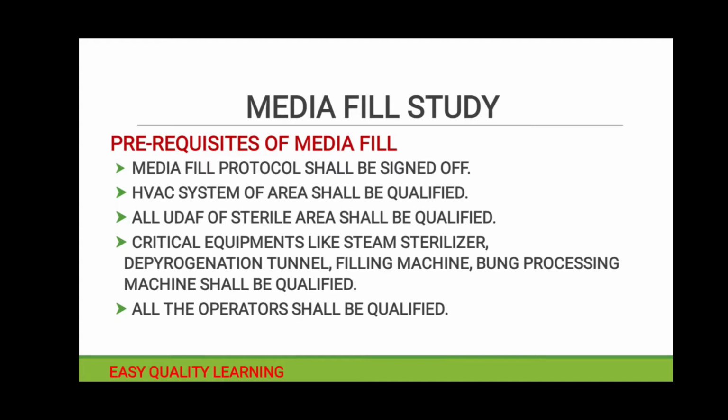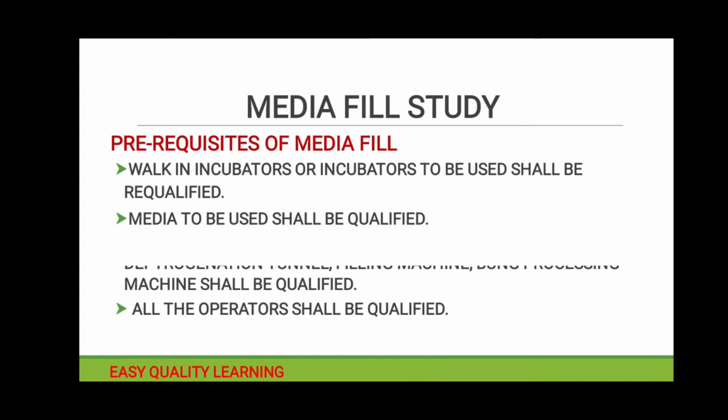Then all the critical equipment which is used in aseptic processing, like your steam sterilizer, depyrogenation tunnel, filling machine, and bung processing machines, all these machines shall be qualified as per their requirements. All the operators who are going to participate in your media fill should be very well trained and qualified, and they should be explained how the activities have to be done during aseptic processing.